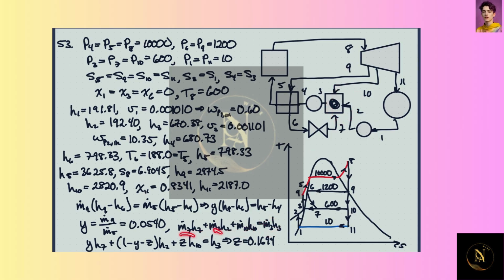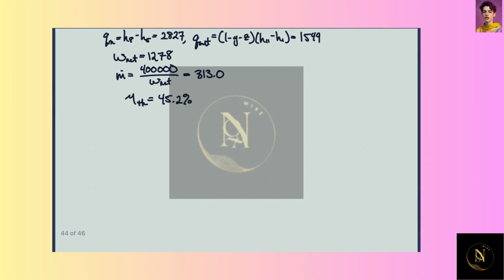So we know the mass flow rates here all have to add up to the mass flow rate there. So we've got to use conservation of mass too. And so that gives us an equation for Z, which is Z is m dot 10 over m dot, what were we using, 5? So we get an equation here where we know everything except Z, so we can get Z is about 17%. So we're taking another 17% off of there. And so now we have our enthalpies everywhere.